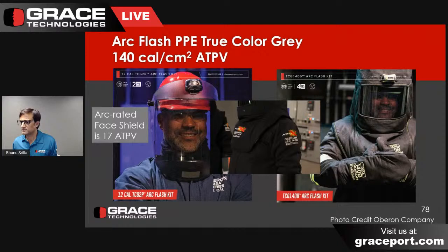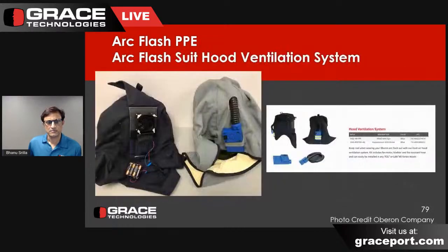That 50% probability of the onset of secondary burn injury goes down when you have a higher ATPV class suit on than 40. This is a whole area of opportunity here for industry across Canada and in the US. Do a risk assessment. We can have qualified persons working at higher incident energy levels with the same 50% probability of onset of second-degree burn injury as an 8.7 cal coverall. Next slide.